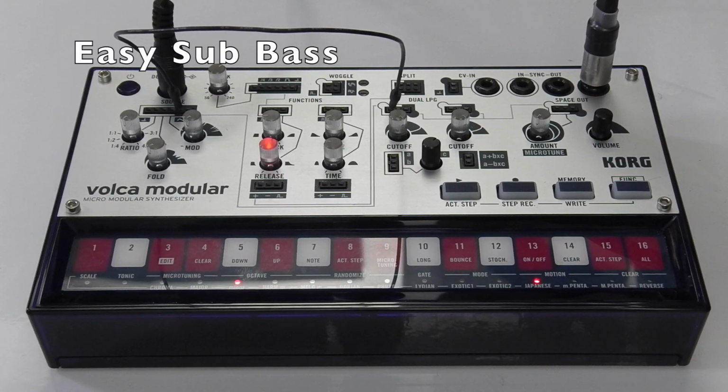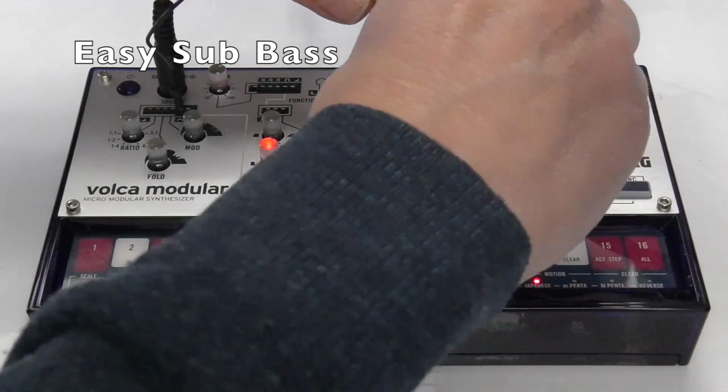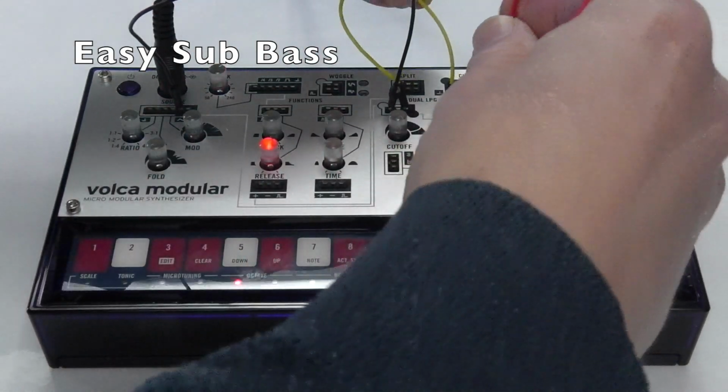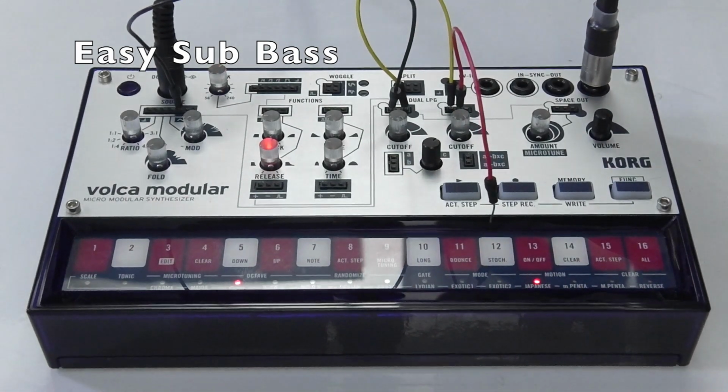So if we connect the LPG1 signal output to the LPG2 signal input, and then if we also duplicate the default connection from function 1 that is going to the LPG1 level input, if we duplicate that to the LPG2 level input, that will get the volume envelope to make that audible. So we will duplicate the wave in LPG2, join them together, and the result will be a louder sound.